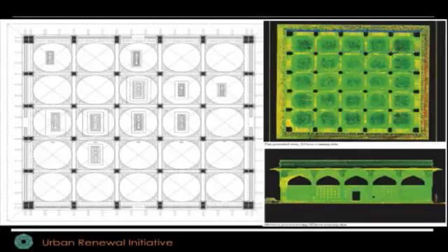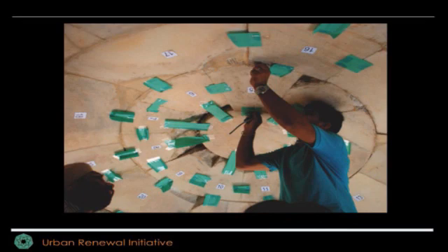And so we had to, this is the plan. So you have these 25 domes and 4 columns in the corner and 2 columns in the outer facade and 64 columns. So this is a laser scan of the roof. And these are the cavities. After you take out the cement, you can see how big the cavities were. These were the cavities, and obviously the stone was not going to survive too long.